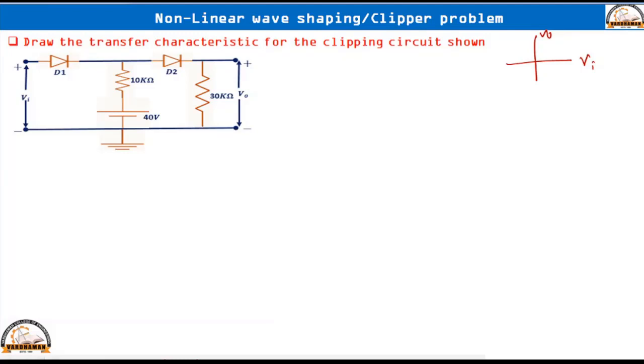See carefully, first observe the circuit. We have two diodes. When you know about the on state and off state conditions of the diode, then we can easily get the relationship between V0 and Vi. That means for what input voltages diode D1 will be in the on state and diode D2 will be in the on state. If it is in the on state, we can replace the diode with a short circuit by assuming ideal diodes, and then we can get the relation between output and input. Similarly, you need to know for what input values the diodes will be in the off state. This is what we are going to see.